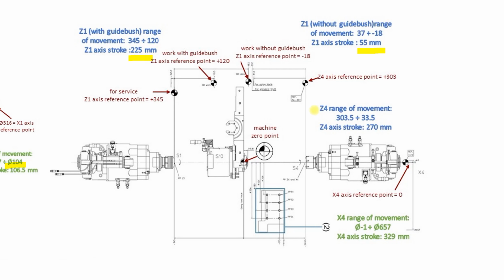In channel 2, the range of movement is described here, and stroke equals 270 millimeter. This lower value, 32.5, corresponds with use in channel 1 standard stationary cutting tools with cross section of 12 by 12 millimeter.